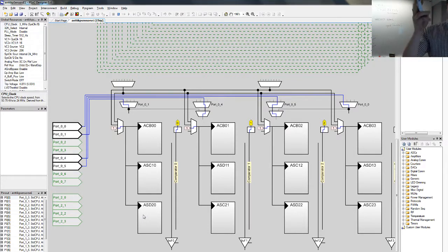Then on analog, okay, analog inputs are on the left hand side again, and as you can see, the number of pins is limited. So if you have a mixed signal application, you should use port 0 for any analog input and select those first, then see what pins you still have available for digital.